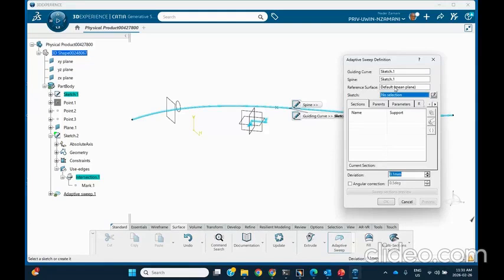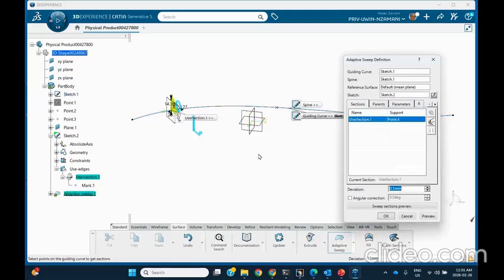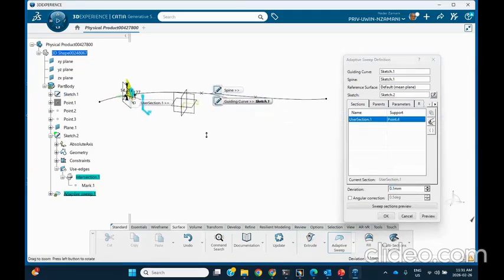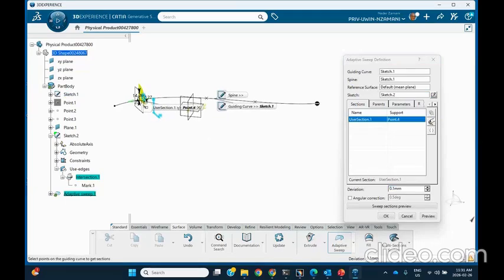There is no reference surface. There is no surface that I'm using. So you use the default surface, which is something called mean plane. That's okay. And the actual sketch is right there, this circle. Now, assuming that this circle, when it's swept, does not cause any self-intersecting situation. For example, if you look at the preview, there we are. But that's not what I want to do, okay?